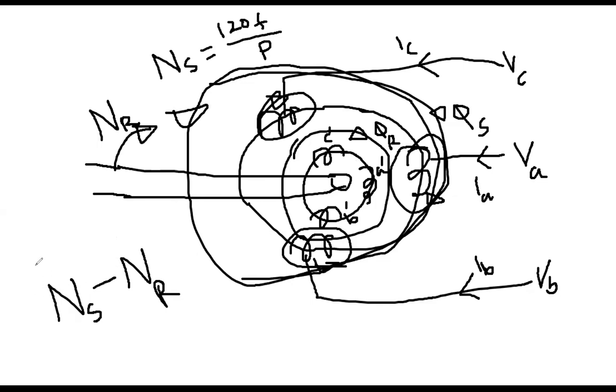That difference is called the slip speed, as you saw in the previous slide. Slip speed does not mean you fall down or slip. It's just because the rotor field lags behind the stator magnetic field. First you apply voltage here, consequently phi s is developed, so it has higher speed than nr, because nr depends on phi s. If you don't apply voltage, there will be no phi s, consequently no phi r, no interaction, no torque, and hence no speed on the shaft.